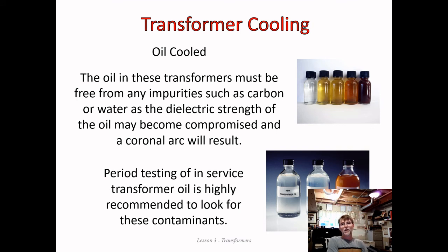Now, the oil in these transformers has to be very carefully monitored because it must be dielectric. Because the coil is submerged in this oil, we don't want that oil to be conductive. When you're doing regular maintenance of your transformer substation, and I was involved in this for years, typically once a year the substation would be shut down, and we would go in and clean every surface. All the dust has to go, because dust is probably conductive, and if you put dust on the insulators, it reduces the insulation value of the insulator, so all the dust has to be removed.